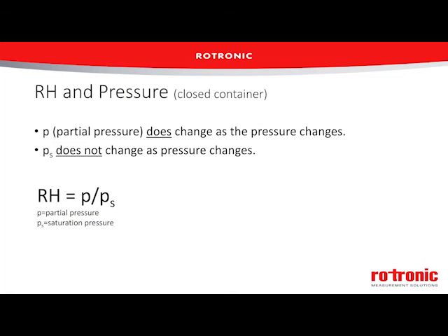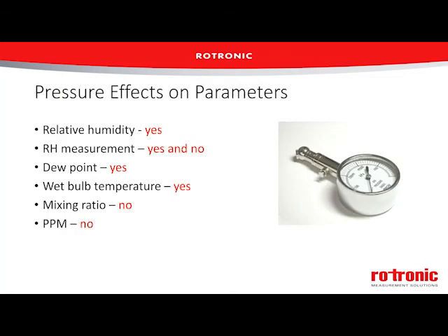So in this case, we change the total pressure, our partial pressure is going to increase, but our saturation vapor pressure stays the same. And this is what causes the change in relative humidity. So pressure affects us different ways depending on what we're actually measuring or trying to report.